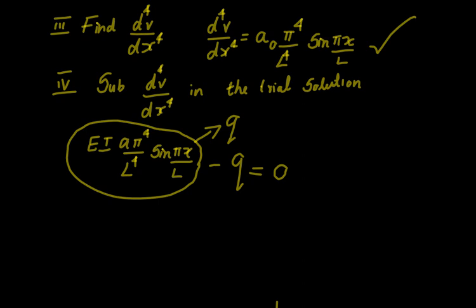And you have to fix that x at L by 2. That is point collocation method, which means only at that specific point, this particular left hand side becomes q. At other points, it is not equal to q. There is a residual rate of loading. It should be equal to q, but if it is not equal to q, then it is a residual rate of loading. If this sounds confusing, maybe just pay close attention and listen to this again and again. It will make sense.